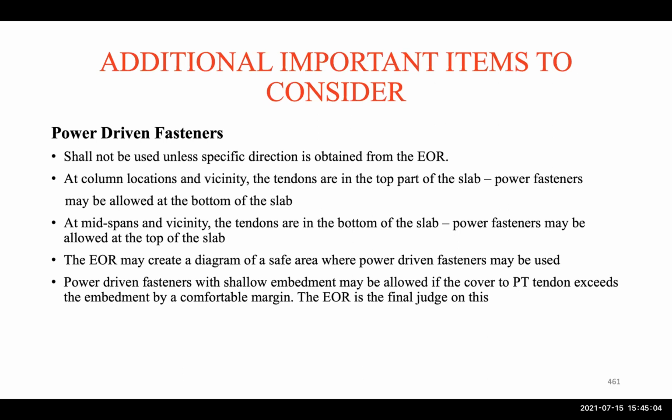So power driven fastener, the same thing. Here we have to be careful about the layout and the location of the tendon. If it's in the middle of the span, we know the tendons will be at the bottom, so we have to be careful. We can put things on top of the slab if needed. If it's close to the column, we know the tendons will be at the top.